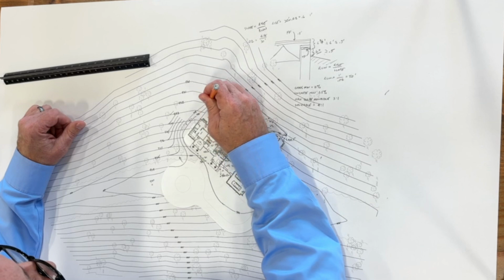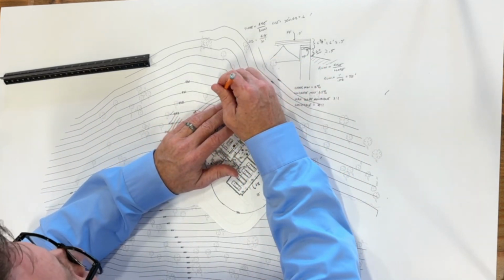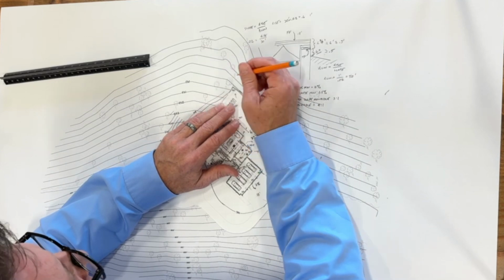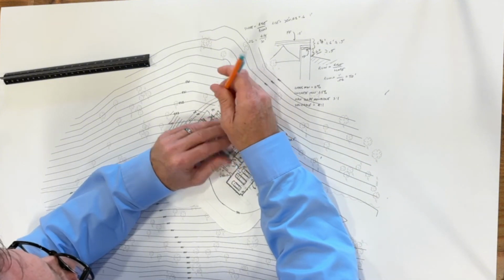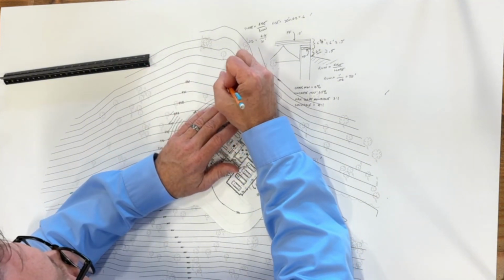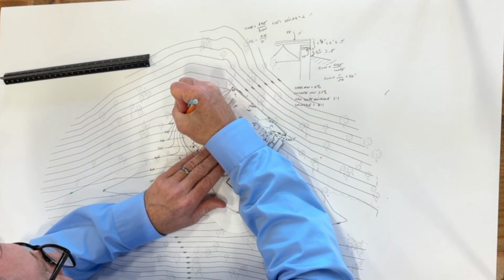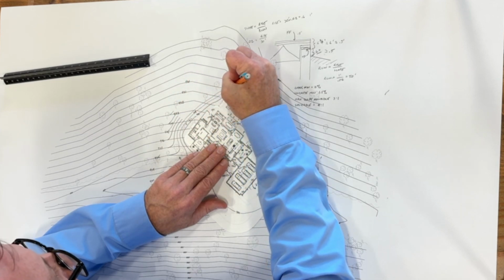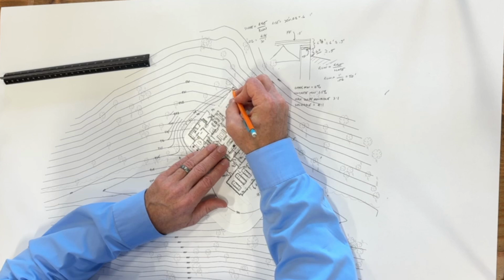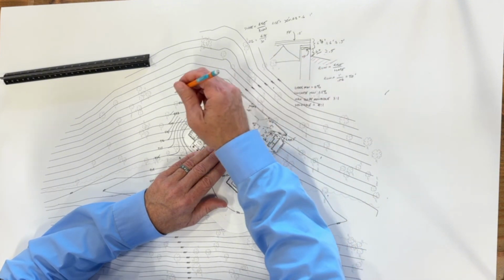So I'm going to carry this around. Now, this retaining wall is designed to basically allow the ground to just drop behind it. So I'm going to start swinging these guys in. So I'm going to say this guy comes like this, and then a 938 comes around and just dies in. And again, we don't really care when it dies in at the end. These can be steeper because heck, it's a retaining wall anyway. And so you're not worrying about mowing anything down there.